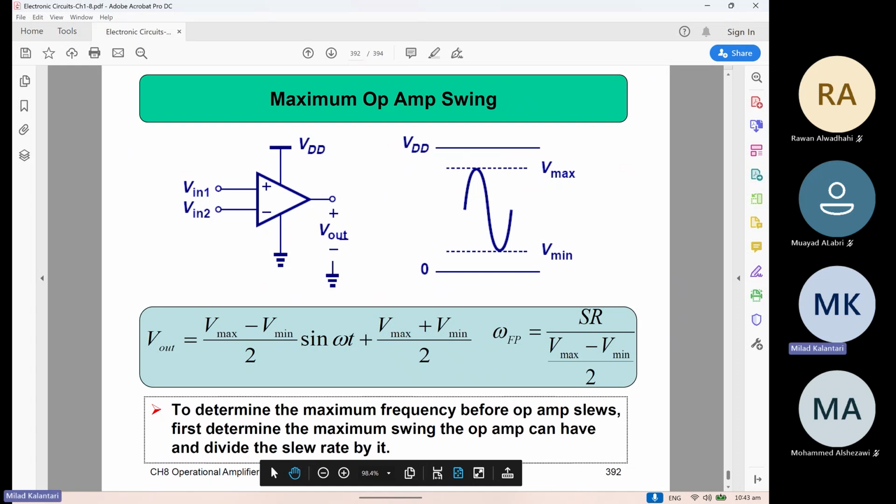So we have another constraint for the op amps that is more clear. The op amp has some biasing supplies, and then we usually expect that the output of the op amp can reach at least the minimum, the negative supply, or here it is ground, and at the max can reach the VDD, the maximum voltage that you have.